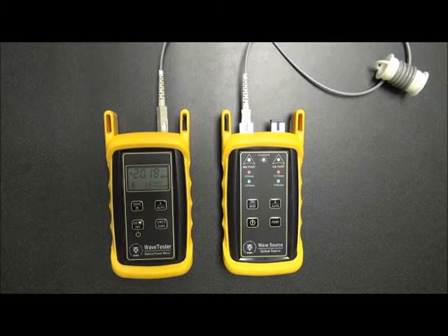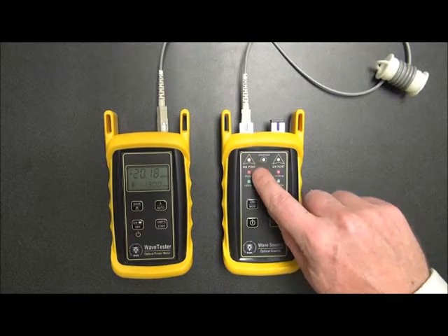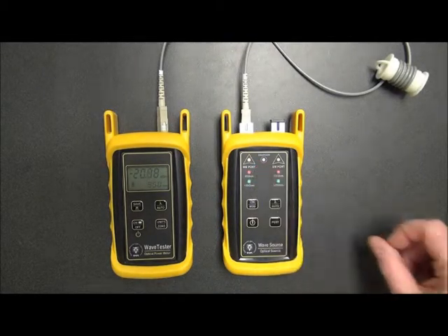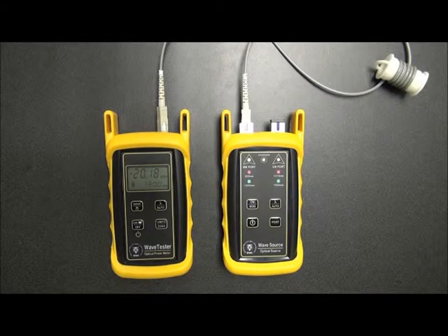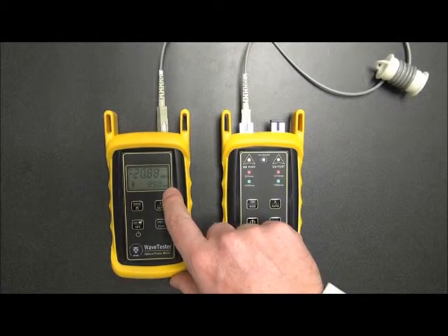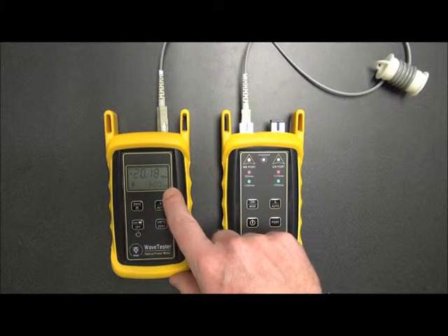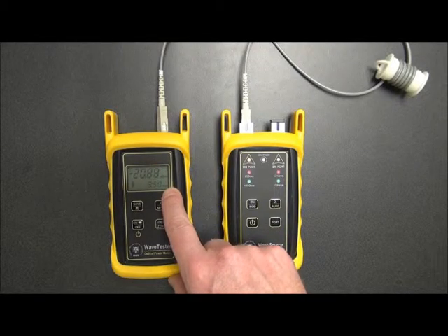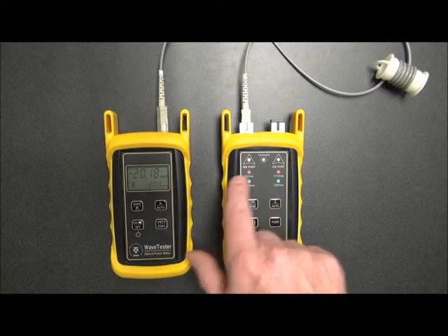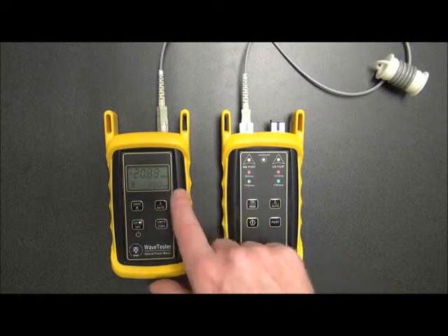So the WaveSource is in auto mode, and if you look at the WaveSource, it's alternating between colors, so red and green, so it's putting out 850 and then 1300, and it's also alternating between flashing and solid. And this basically is the rotation of wavelengths that the WaveTester needs for its measurement. As you can see, the WaveTester is indeed switching between 850 and 1300 now. If you look, when the red is on, 850, so the red light here is on, means 850 is here. If the green light's on, then it's 1300 here.